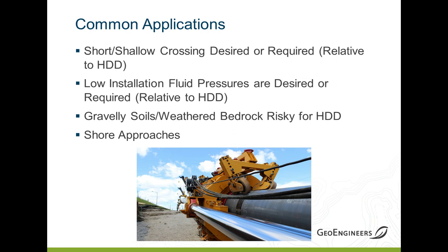a strong market that's developing for direct pipe, and we'll talk about one that we did because we couldn't get the HDD permitted. We couldn't meet the required factor of safety against hydraulic fracture with HDD, and so we went to a direct pipe, and so we're seeing more and more of those crossing under predominantly levees, but the same principles would apply to any sensitive surface feature.